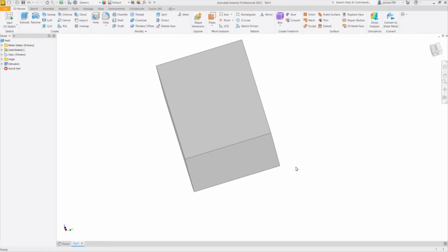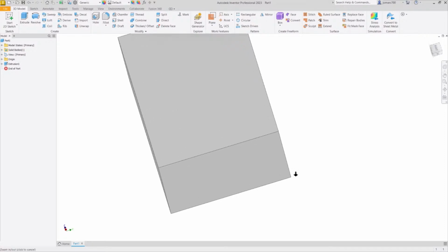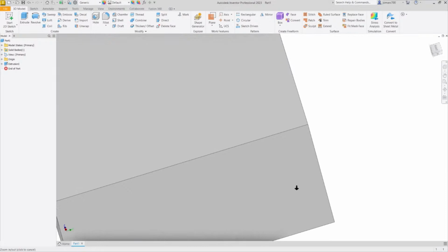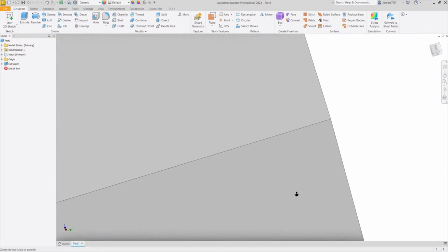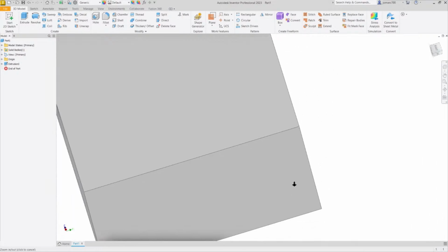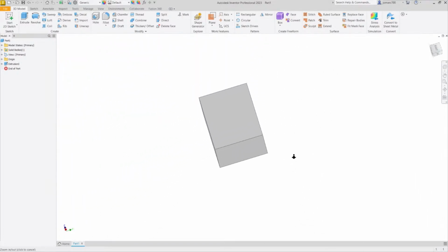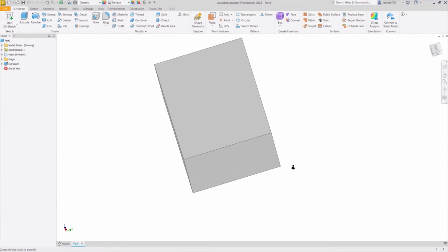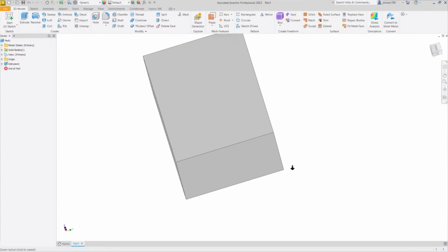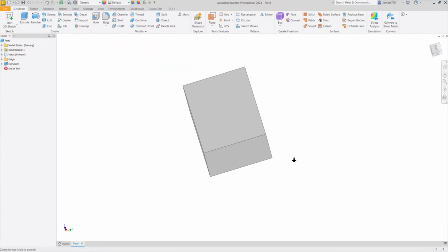In addition, to do a fine-tuned zoom in or out, it's pressing F3. Once more, F3. So notice the change in my cursor. With that, I can hold our left mouse button, so simultaneously F3 and left mouse button. I am zooming in if I move my mouse towards me, and if I move my mouse away from us, I'm zooming out. So this is a fine-tuned zooming in and out by holding F3 together with your left mouse button.